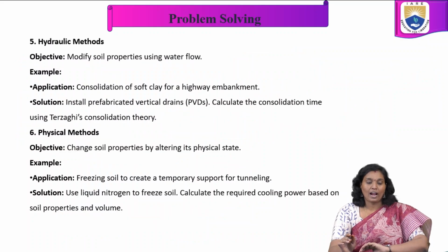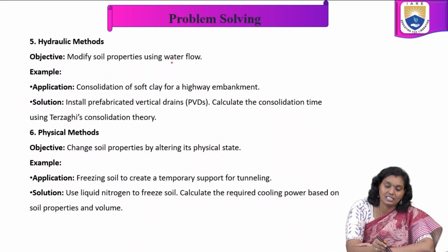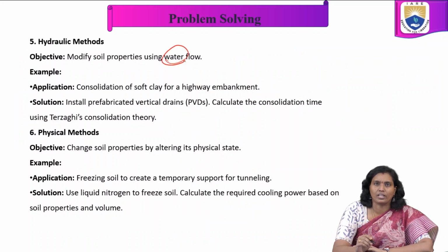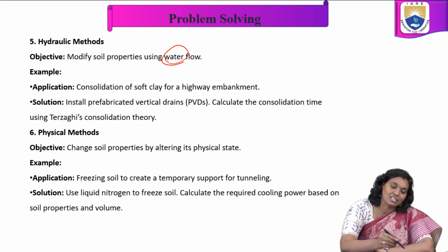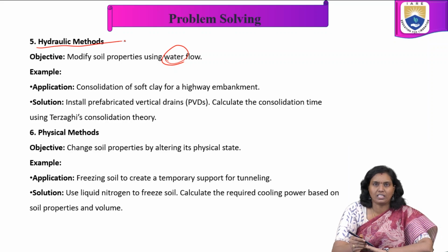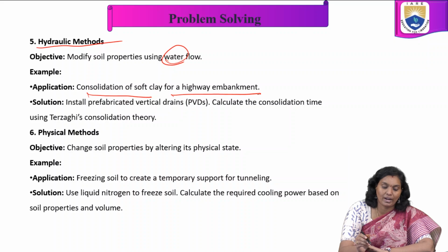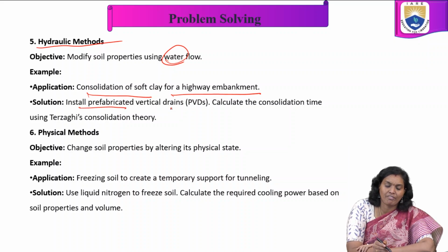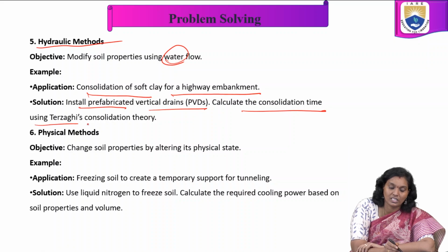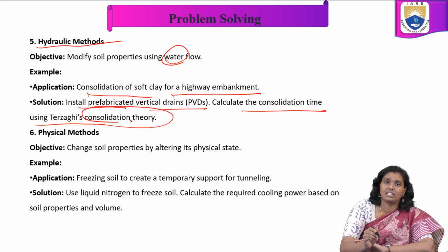Now hydraulic methods. The hydraulic methods come under water. They modify soil properties using water flow. Such type of categorization comes under hydraulic modification. In this, consolidation of soft clay for a highway embankment. Install prefabricated vertical drains. Calculate the consolidation time using Terzaghi's consolidation theory.